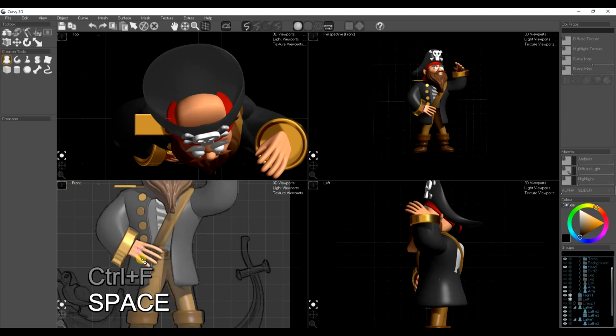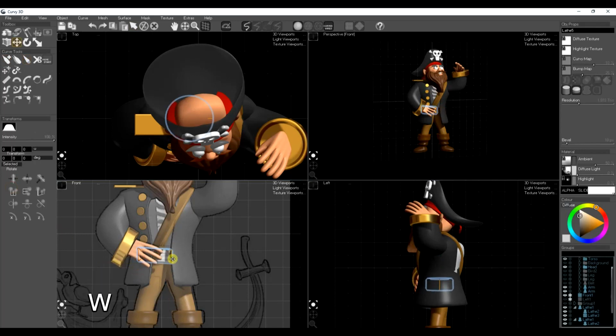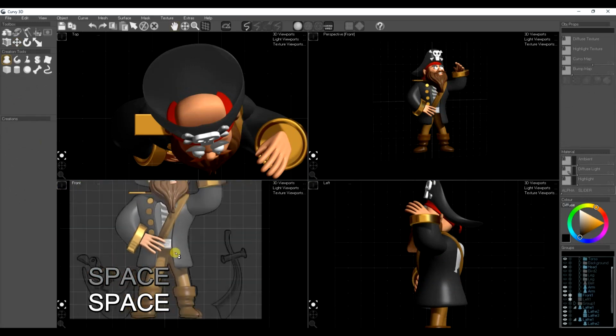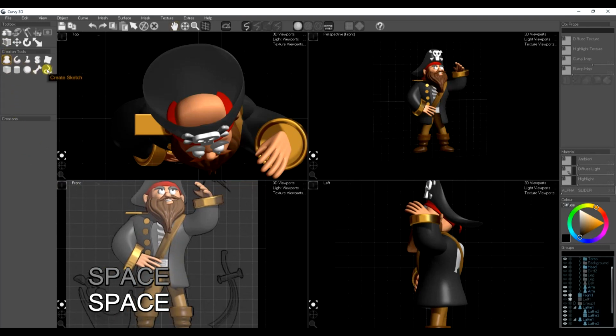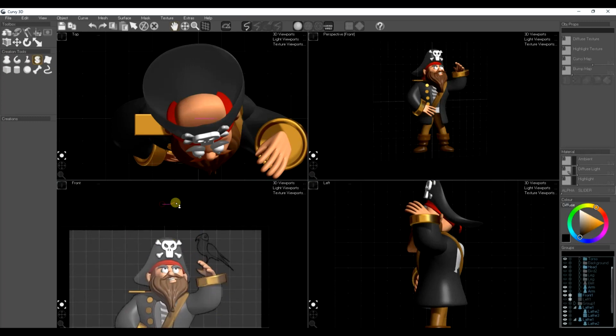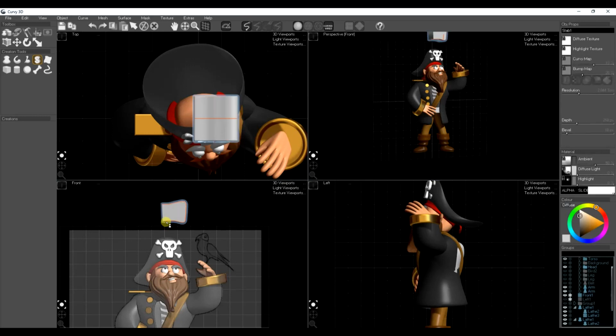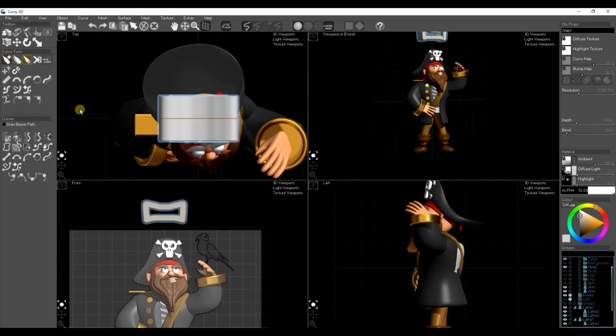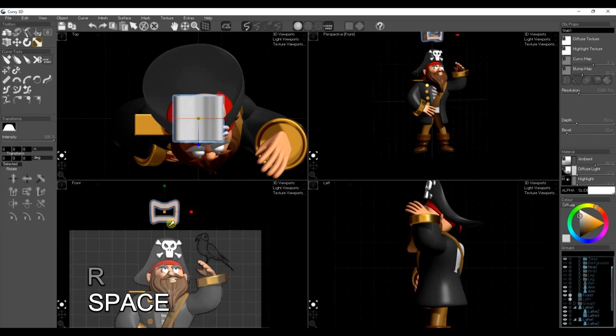Let's draw his belt. Again, it's that sort of sharp C shape. Quick belt, and then we want a belt buckle. So I'm going to zoom out and draw the belt buckle with a lathe, with a slab. So drawing one half of the buckle and mirror X to make the other half, curve offset to make a sort of an inner curve for that buckle, press S a bit to smooth it and move the inside bit of the buckle into place.